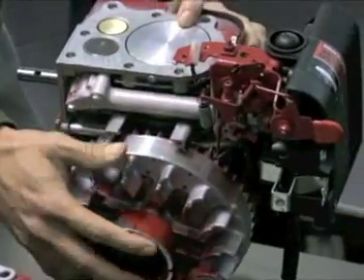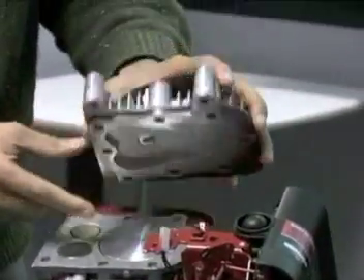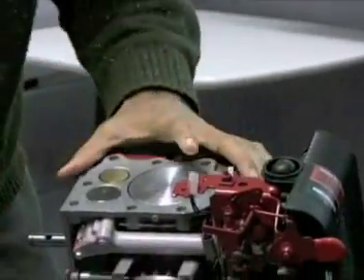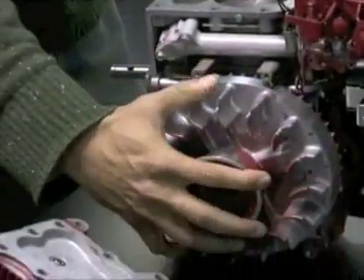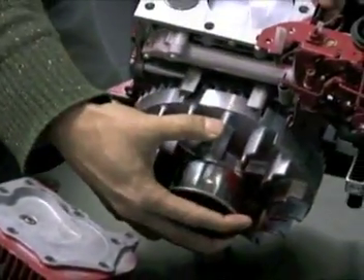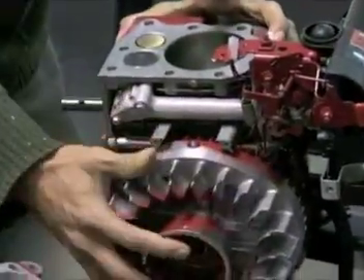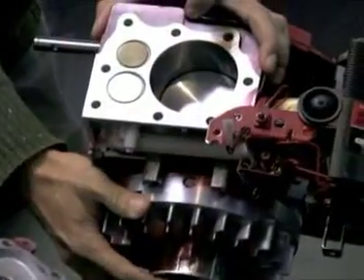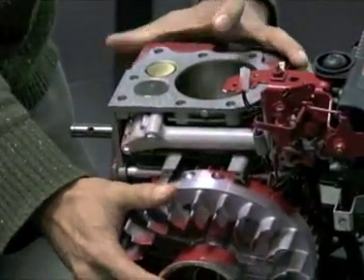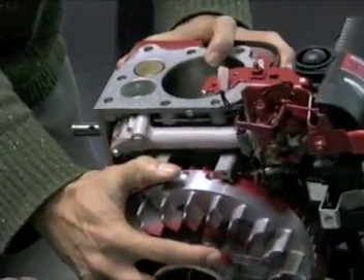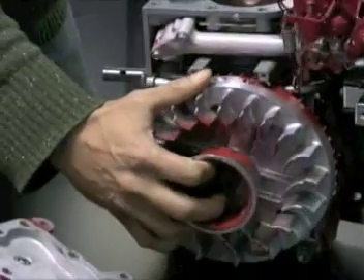At this point, the spark plug would ignite the air-fuel mixture right here. That will cause an increase in temperature and pressure, which will push the piston all the way down, and it keeps going down till it reaches the bottom dead center. This is called the power stroke or the expansion stroke. Once it reaches the bottom dead center, the gas has completely expanded and it has nowhere to go.